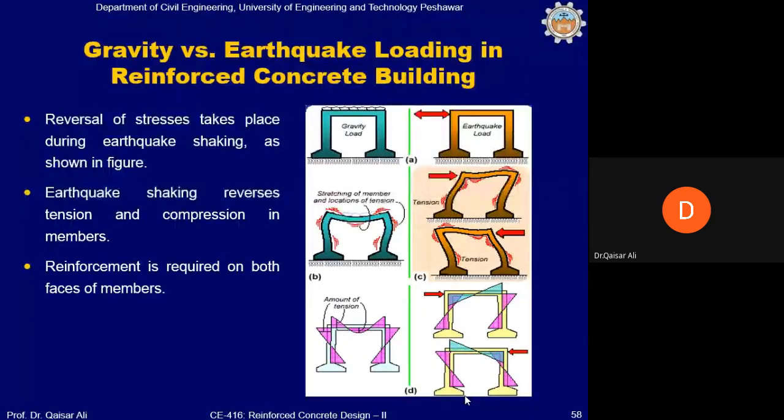In order to avoid this corrosion, sometimes the steel bars are epoxy coated, and these epoxies are basically corrosion inhibitors. These corrosion resistant epoxies are very smooth in nature, and they increase the smoothness of the bars. When they increase the smoothness of the bars, the bars can be pulled out very easily from concrete.